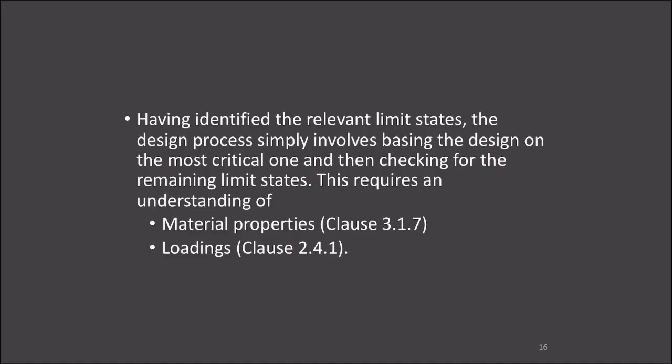Having identified the relevant limit states, the design process simply involves basing the design on the most critical one and then checking for the remaining limit states. This requires an understanding of the material properties. So in the British Standard, we will refer to clause 3.1.7 and for loading, clause 2.4.1.